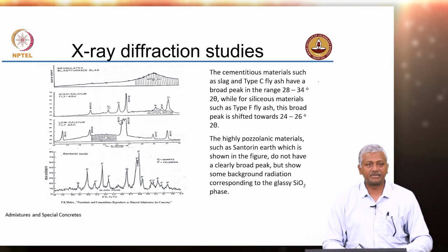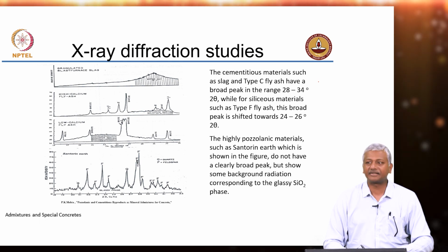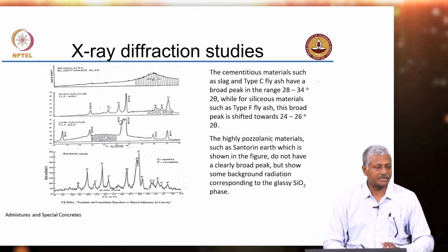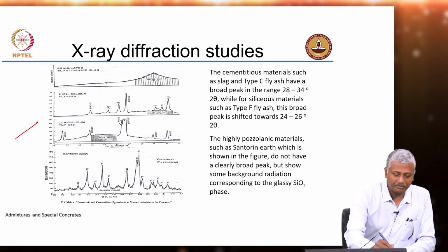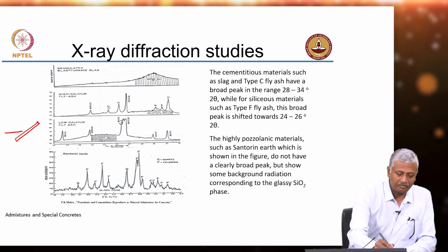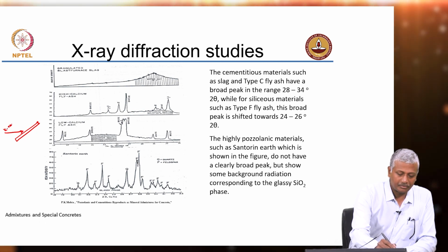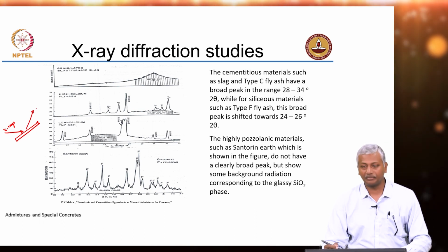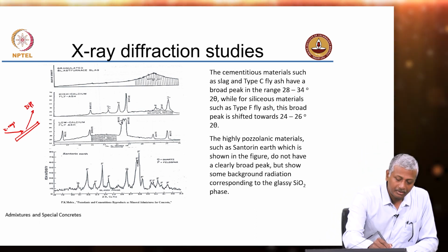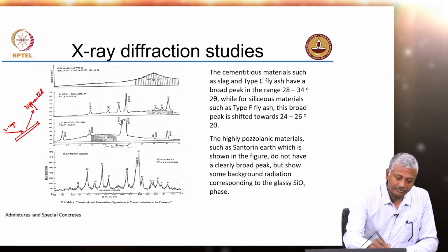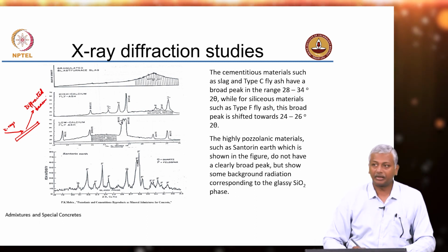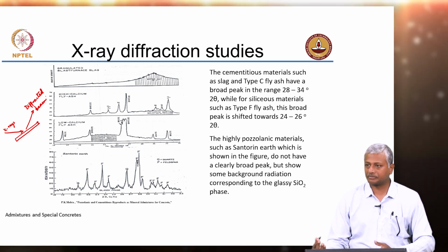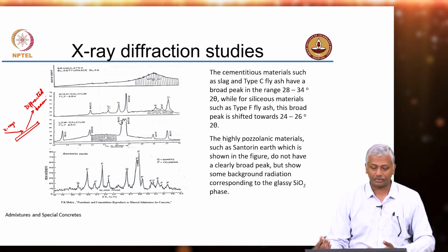Another scheme of characterization that is commonly followed with mineral additives is X-ray diffraction. Now, X-ray diffraction is a study in which, let us say this is your sample, we have a beam of X-rays that is made to interact with the sample, and there is a reflected beam, or a diffracted beam, we call it a diffracted beam of X-rays. And of course, you may have heard about this law in physics called Bragg's law.